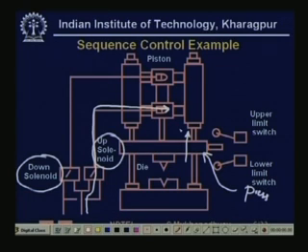Similarly, if the down solenoid is energized, then this press goes down, and this is your metal sheet. It comes down and stamps on it. So, it keeps stamping, retracting, and creating a particular shape of sheet metal. These things are typically used in making, let us say, car bodies, right. So, it is a hydraulic stamp press. Okay.